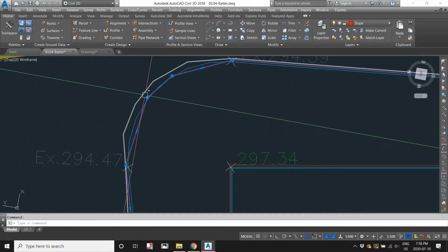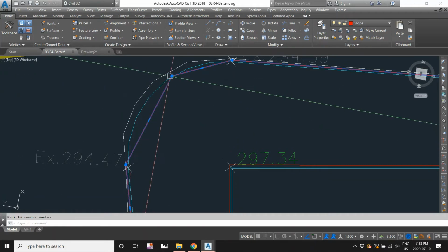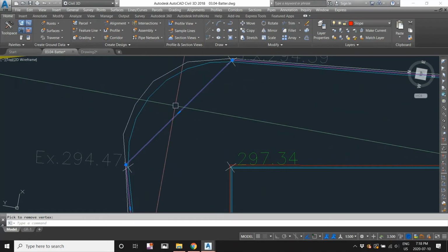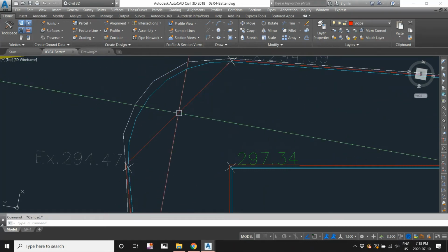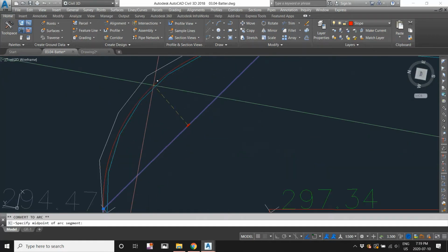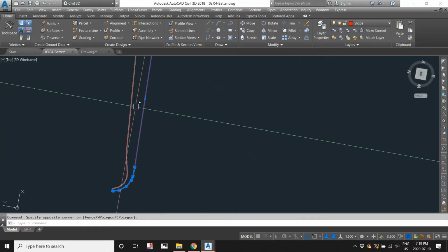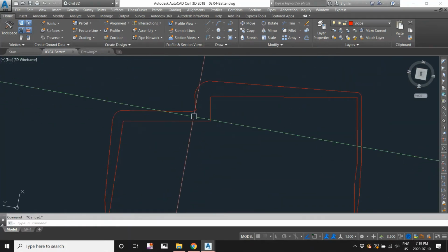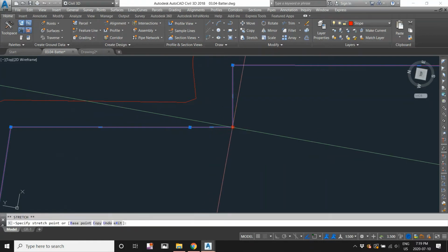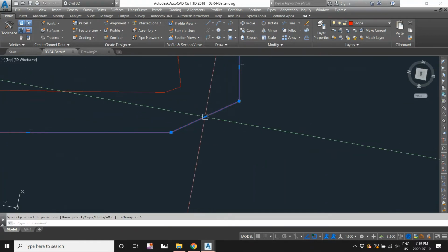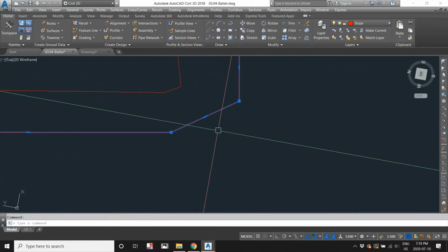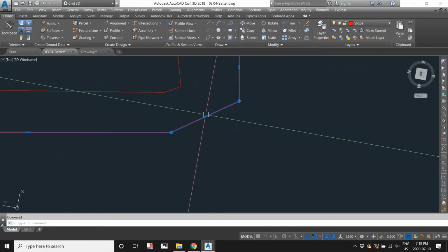Remember, I'm just adjusting the feature line, and on top of that I put these 2 polylines on a layer called slope. So I basically have this top of slope line and this bottom of slope line. And you'll notice with this lesson I have included a file. It's called an LSP file, and I use that file to create my 3-2-1 sloping.